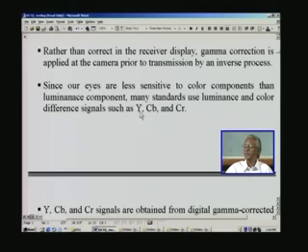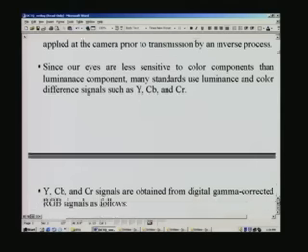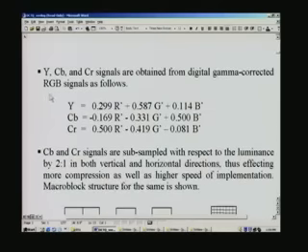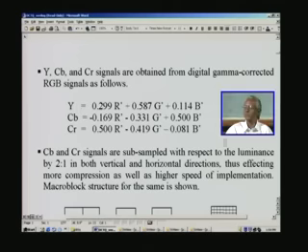The reason is that Y, CB, CR are governed by these expressions here, which are derived from gamma corrected RGB, and gamma correction is indicated with a prime here. These are all the expressions that we need to conform to, and the standards, all the way from JPEG through MPEG-2 and even beyond, demand the use of the YCbCr format.